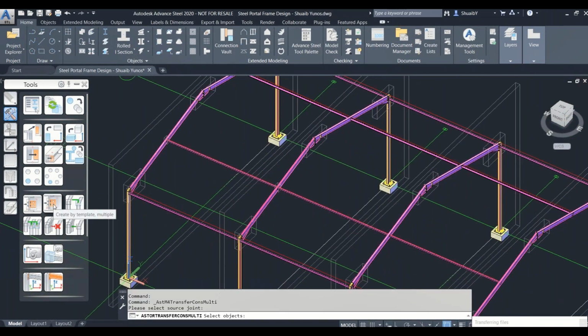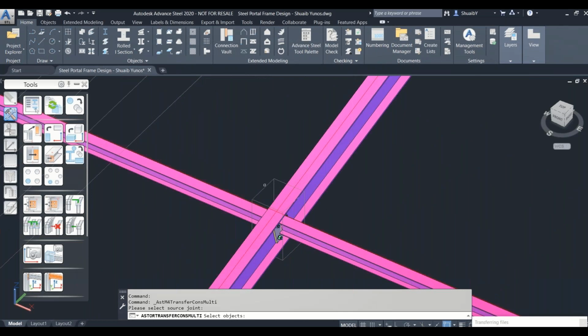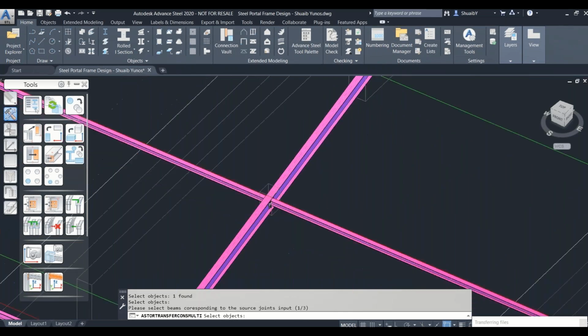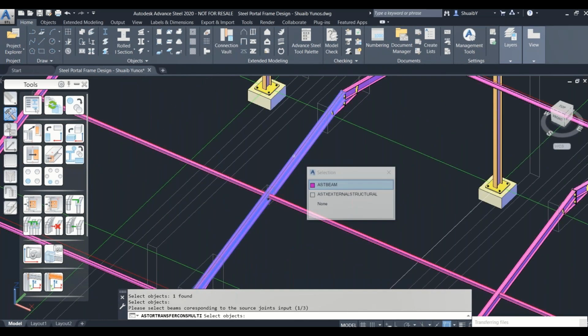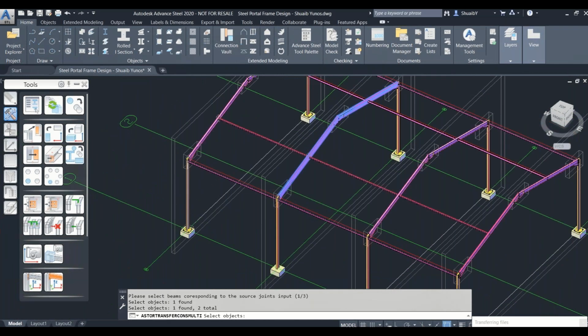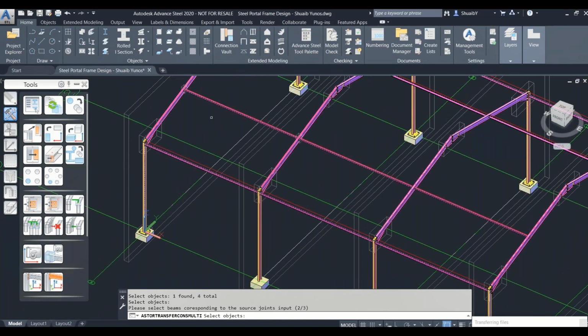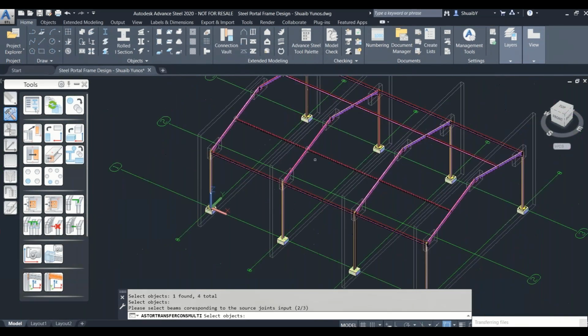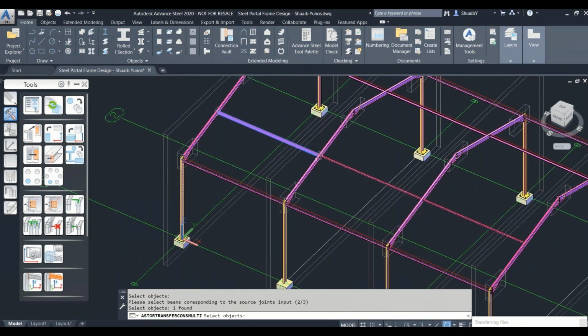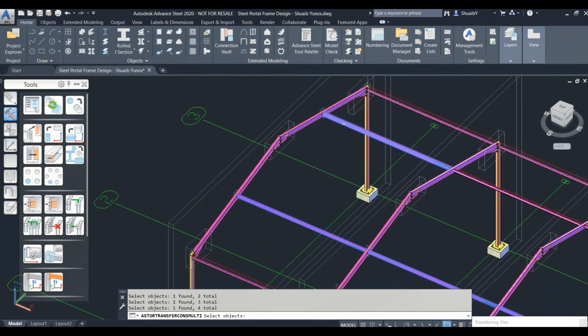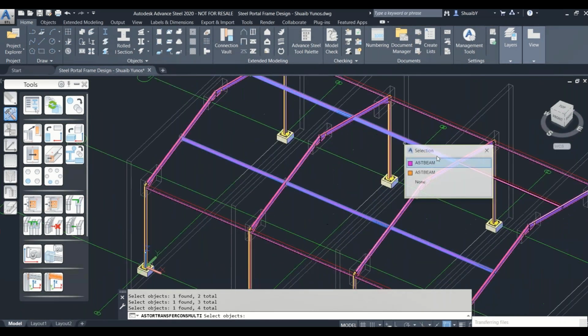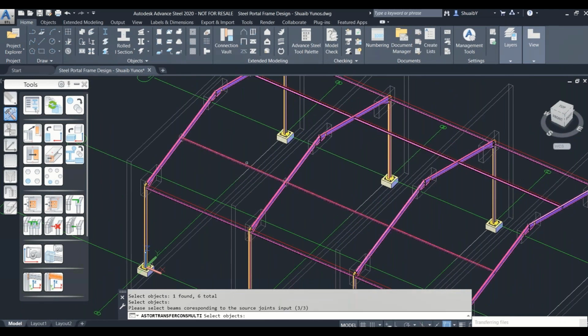So we can use the multiple copy, create by template multiple. We're going to select the joint that we want to be defined at those points, and it's going to be attached to those steel trusses, if I could call it that, right? So I'm just selecting them. So those are the ones in question. These are just the elements that are contributing towards it. Okay, so the ones that we have created and copied, offset at I think 6,000, or 6 meters. Okay, so let's just go and select them. So those are the ones that need to be affected.